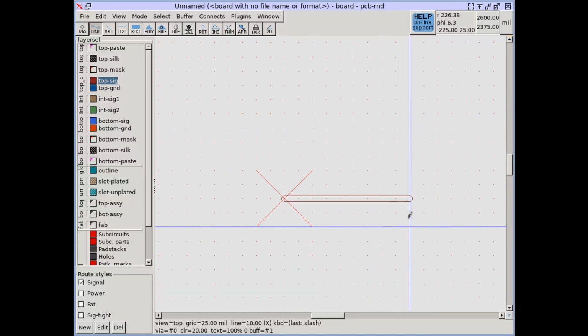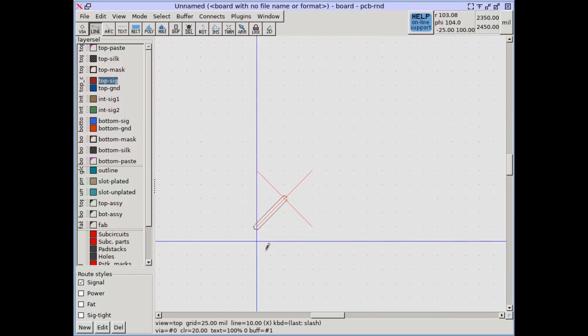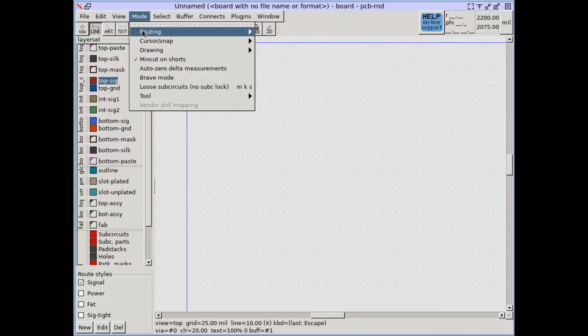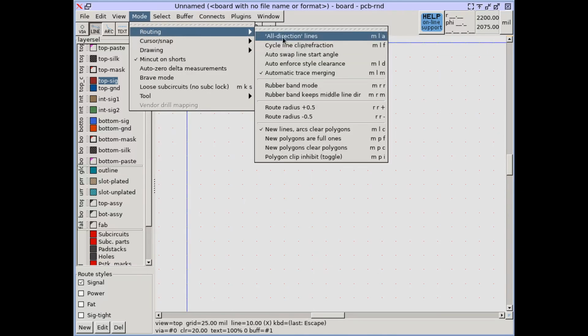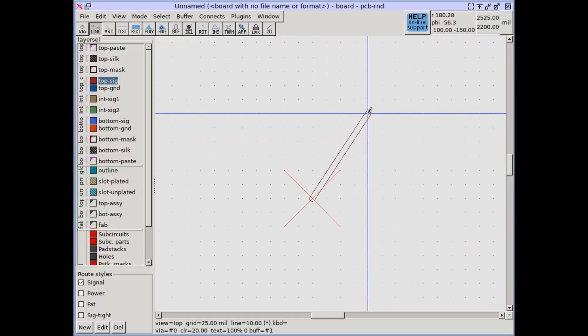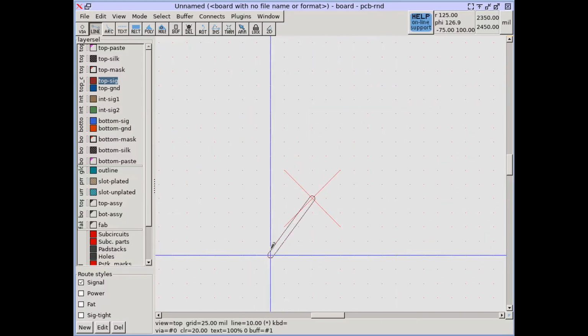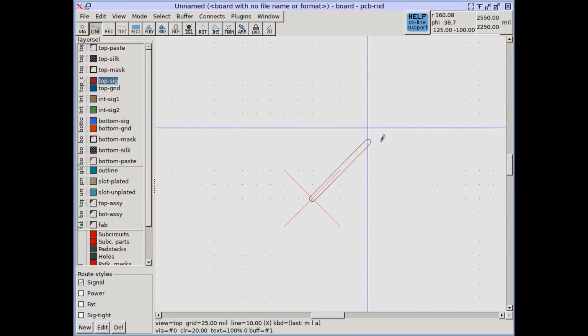In the X mode, there is no refraction, but a straight line from start to crosshair in 45-degree steps. The all-direction lines mode turns off limiting line slopes to 90 or 45 degrees, and there's always a straight line between start point and crosshair.